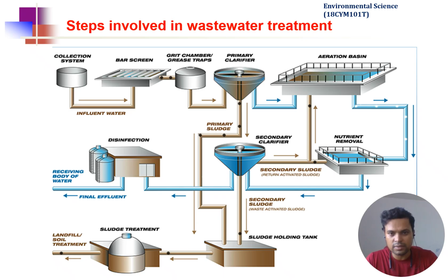And then we have the aeration tank, where we have the biological treatment process. In aeration, we bubble a lot of oxygen through the water so that we can infuse a lot of oxygen molecules, and the water will contain a lot of microorganisms or bacteria that will digest the small organic particles present in wastewater.